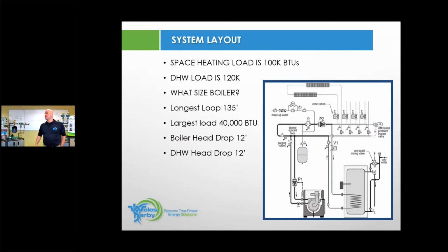Oh, John, yes, sir. Just a question came up randomly, but what would be a good recovery time? What would be something that we would shoot for? Most indirects, if piped properly and pumped properly, you're probably in that 11 to 13 minute range. A typical 40 gallon indirect will absorb about 150,000 BTU depending on the brand. So if I'm driving it to full capacity and I'm going to support that first hour delivery and recovery, somewhere in that 11 to 13 minute range should be really good.